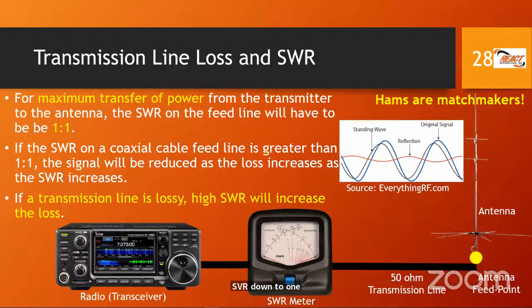There are practical limitations sometimes, but the whole idea is to try and reduce the SWR as much as possible. You're trying to aim for 1:1. It may not always be possible to get 1:1, but you're aiming for as low as you can go, right? All right, so